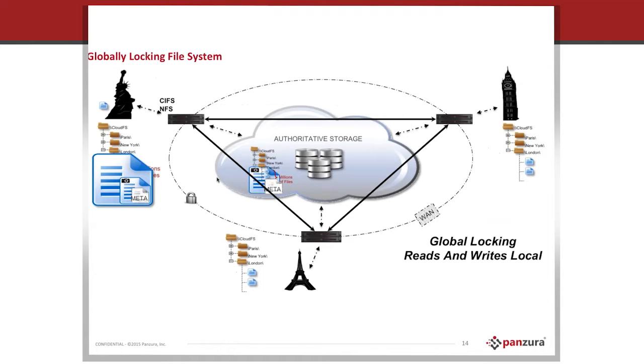In our solution, what's happening with Revit is, although it wants you to believe that multiple people are editing the same file at the same time, what you're actually doing is creating a local copy. You'll always notice that checkbox at the bottom of the file open box says create new local. And whenever you open a centrally shared, work shared model, and you create a new local copy, it copies it down to your laptop or desktop.